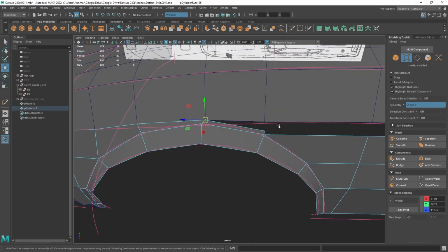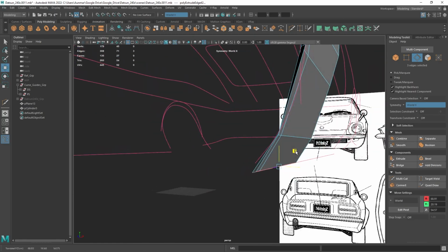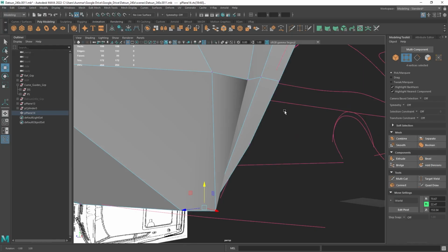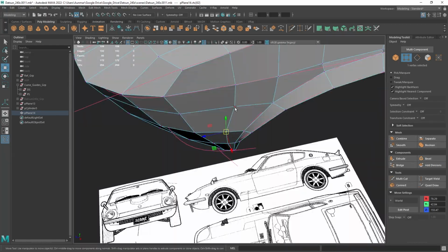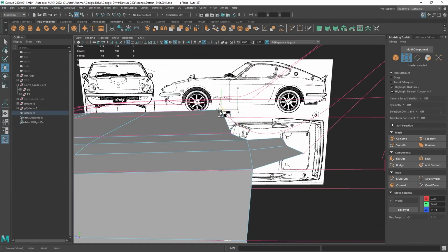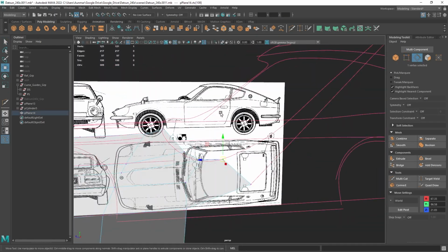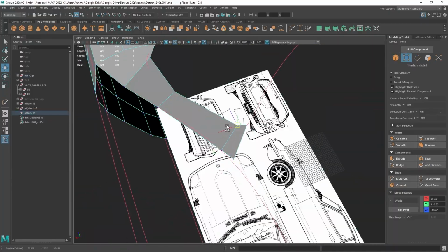And so here I am, again, just using the edge copy, making my way. And once you get to that front fascia, the front fender area, it starts to go really fast because you essentially laid out the base form of the vehicle. And then now we're just going to take that existing topology and start to do things like detail out the hood. And then we can see I'm going ahead and working on the roof of the vehicle.